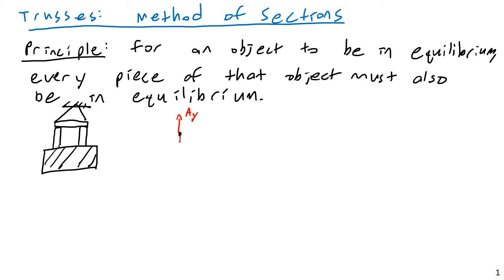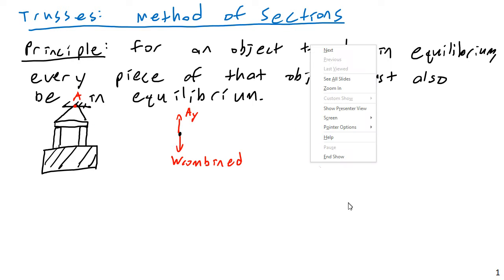And then maybe there'd be the combined weight here. So if I take equilibrium at this point right here, that would be just a support at point A, and then the combined weight of all of these things. And so that would be fairly straightforward. And that would be the net force in Y with the two horizontal components of the tensions canceling out.